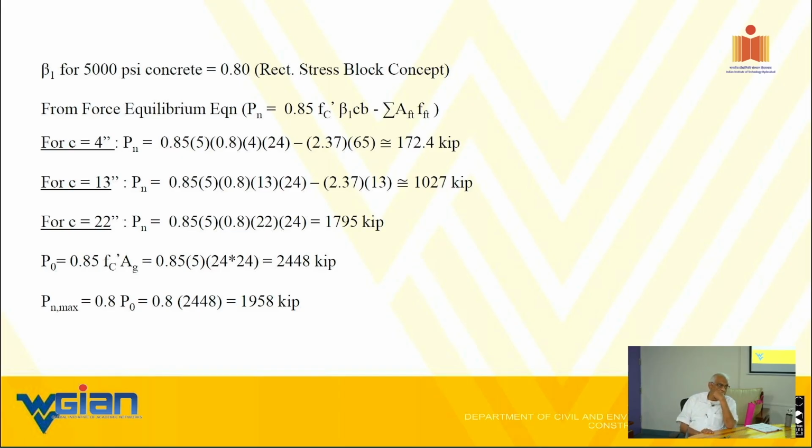If thermal conditions are kept constant, then, sure, absolutely. If the thermal conditions are constant, for example, meaning there is no freeze-thaw type effect, or for that matter, if the freeze-thaw effects are not there, your crack growth or shrinking may be minimal, then you may not have as much of a problem even with steel.